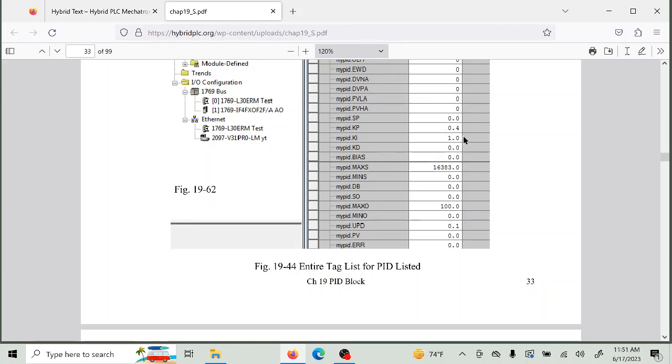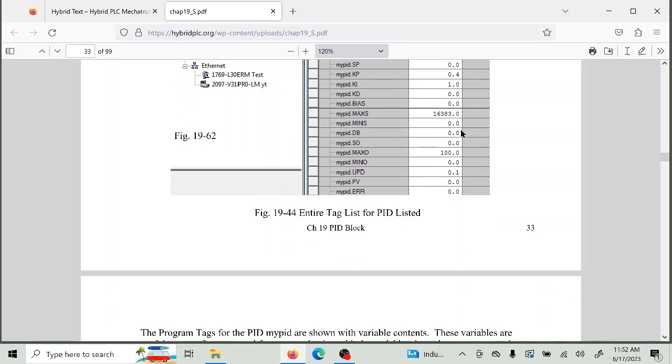Now you say, does this matter? Well, in this case it did, because if I took this number, 0.4 for the proportional term, and went over 1, 1.2 especially, anything above 1.2, this thing went stark raving mad. So you change the set point, and it would go unstable. It would go full on, full off, full on, full off. So just moving that 0.4 up to 1.2 caused that thing to go unstable. Anything over 1 caused it to go unstable. If you moved it past 0.8, it would start to drift. But at 1.2 the thing went totally nuts. Yes, those numbers mean something.